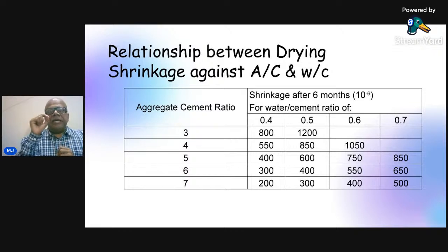What is the actual chemical demand of water for your concrete? So what do I mean? On a site, concrete is being mixed. You put in one bag of cement, 50 kgs, and some water, typically 25 liters of water, so the water to cement ratio is 0.5. Now why do we use so much water? Because we want to mix the concrete, we want to pump it, we want to place it, we want to finish it. So we add a much larger amount of water.